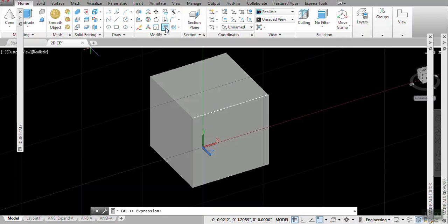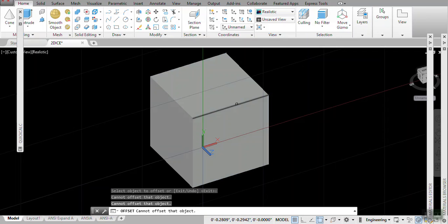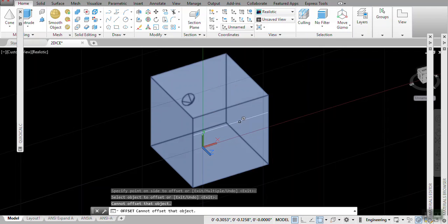The offset command is right now over here, right under the Modify, Offset. Click on it. Okay, there's a horseshoe shape right there, and then when you click on it, the computer will ask you offset distance. So the offset distance is 0.15625. So I'm typing 0.15625. Enter. Okay. Now it says select the object to offset. So I'm selecting that corner, and then I'm picking any point underneath. I'm selecting that last line.